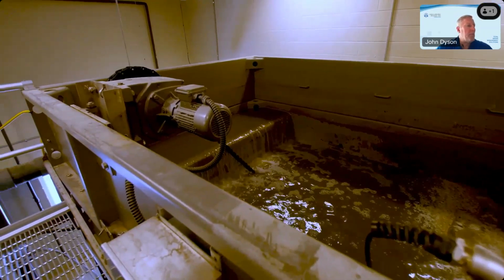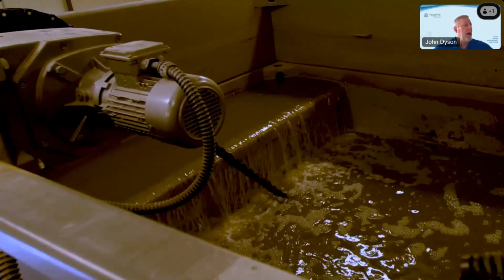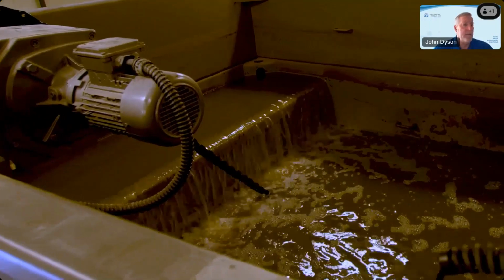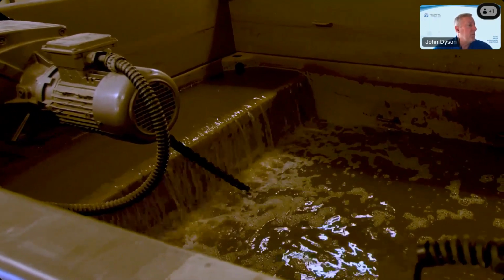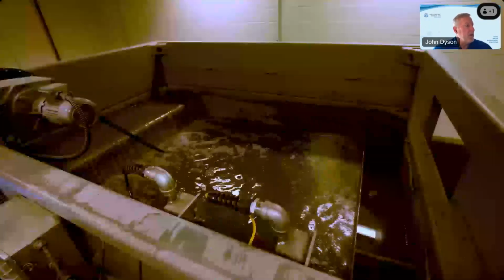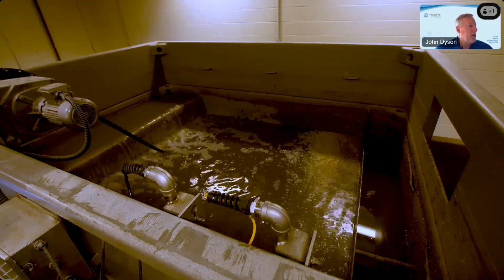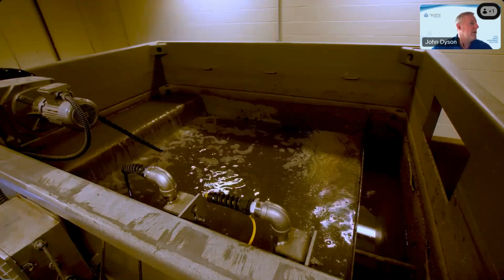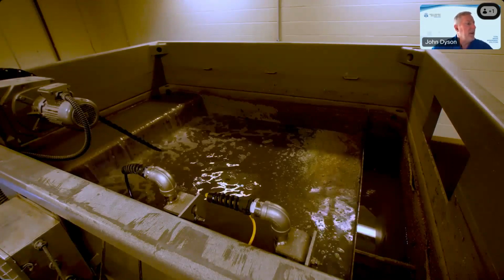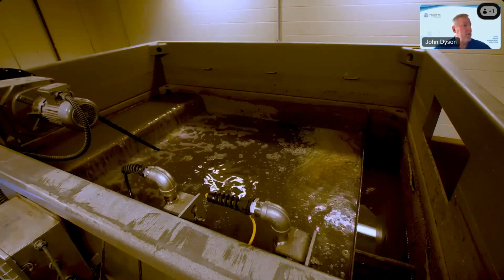So a lot of people kind of want to know what it looks like when it's operating. So here's a video. It's done some time lapsing on it, but basically influent flow comes in, spills over that weir. We're time lapsing, so between the backwash periods, the water level will slowly rise. Okay, here as the flow comes in, you can see on the right-hand side is where the scum trough.